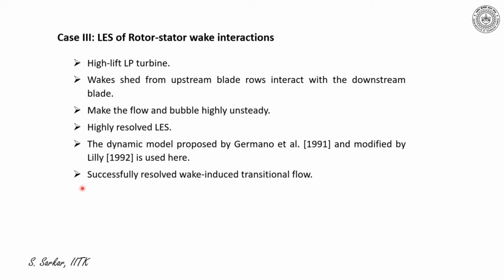The approach was successful in resolving wake-induced transition. It has illustrated the periodic wake as it passes over a turbine blade, inducing an unsteady environment where the transition is multimodal. Multimodal transition means that different modes of transition can coexist at different parts of the blade passage, which appears very complex, and this complex environment has been successfully resolved by the LES.